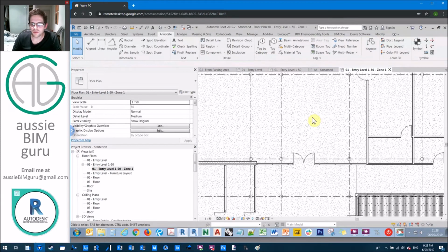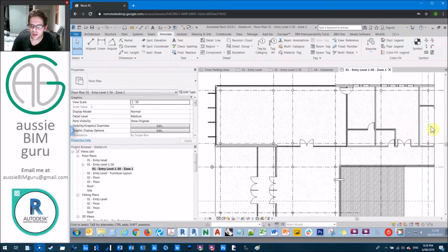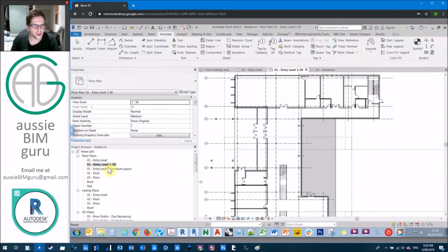So that's how you can maintain common annotations between those in-between zones if you want to see a room tag. But I do typically recommend avoiding documenting around these periphery zones because you will see these annotations bleed into each other's sides if you annotate quite close to these boundaries. So just be mindful which scope boxes you're working in and which ones should have the right tags and elements within them. Because ideally you don't want annotations to be sitting outside your views when they're on their sheet.